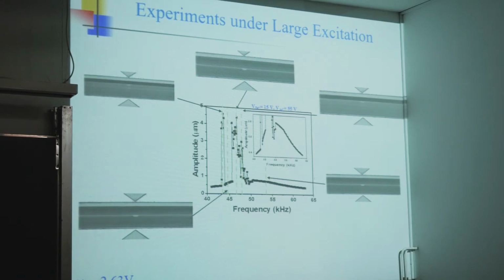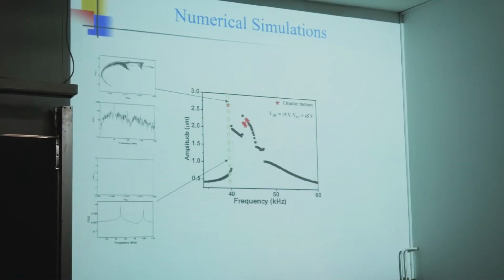And you see evidence of crazy behavior, sometimes very high frequency, sometimes low. These are short video clips. They are qualitative, so don't think too much about them. When I compare this with some lazy numerical simulations using Galerkin, then you see strange attractors, and you see quasi-periodic motions, and you see stuff that, with some more energy, you can apply maybe more robust continuation techniques to study, or Floquet theory and what have you.